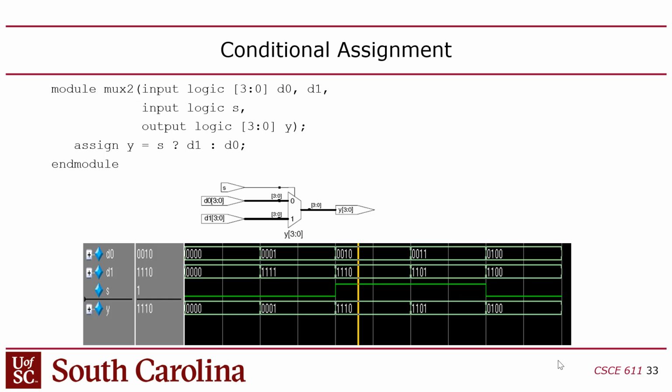Likewise, you have an ALU where the second input can come from the register file or be an immediate. How is that determined? With a mux. So your CPU is basically going to be formed of these muxes with control signals from the control unit controlling the muxes. This is what allows you to steer data around and create data paths for each instruction. Okay?